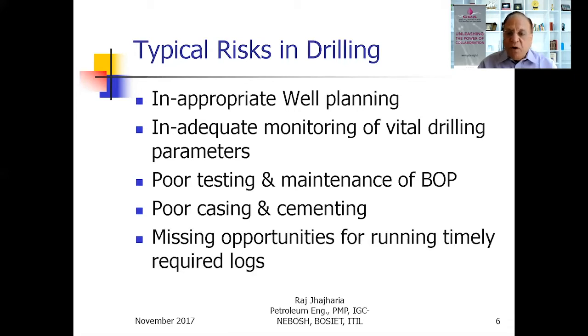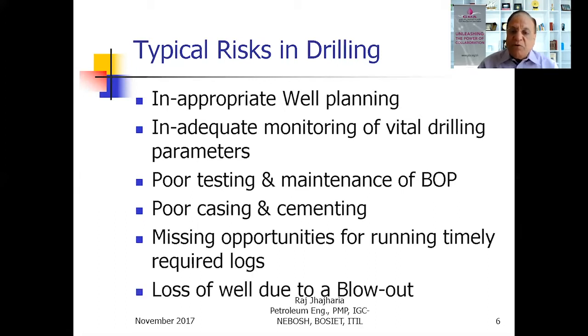And then if you are not using the logging services, which need to be done while your well is being drilled, before you set the casing. If you don't do those loggings at the time of drilling and before setting the casing, you might never be able to get those readings ever after, because once you have set the casing and cementing, you lose that opportunity, and you lose a huge opportunity of collecting valuable data. And you might completely lose the well if you have a blowout. These are the typical risks of drilling.